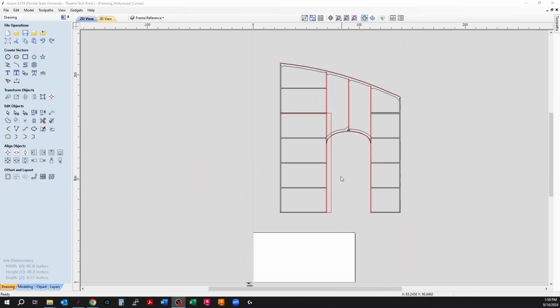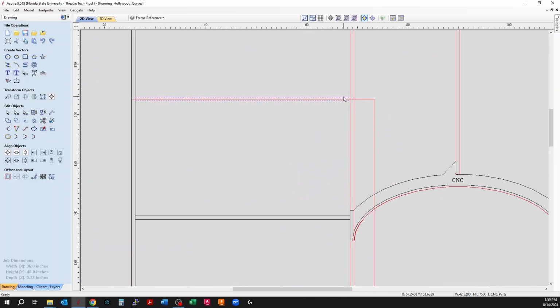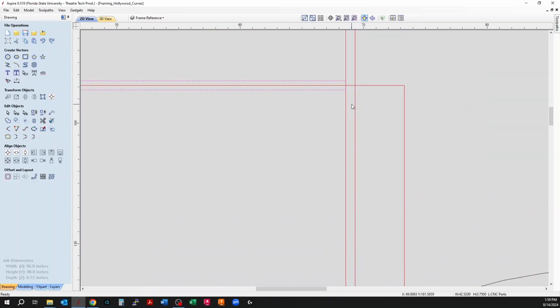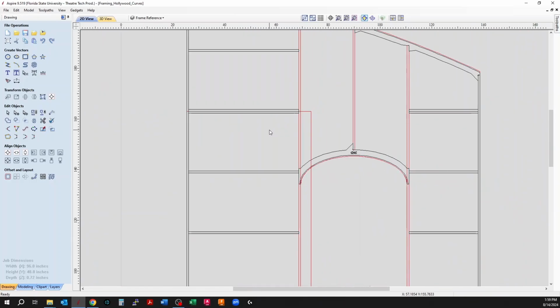Now I've got all the framing in, and I did 2 foot on center framing supports here. Now I've got a reference sheet of 48 by 96 to show where my seam breaks would be. I already did this side, but I'm going to do this side, and I'm just going to select this component and move it right there. Control C, Control V, and I'll do another one there. That way I get a bigger seam break for that. It just can be a little easier.